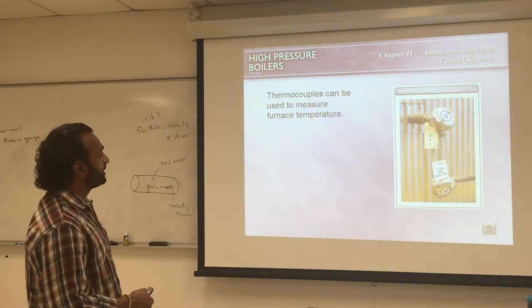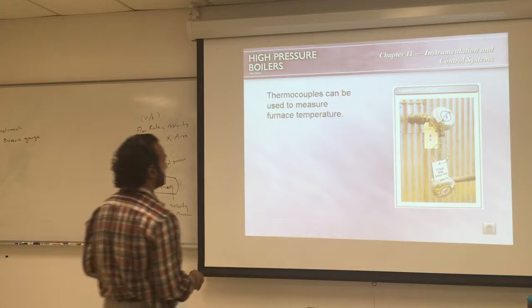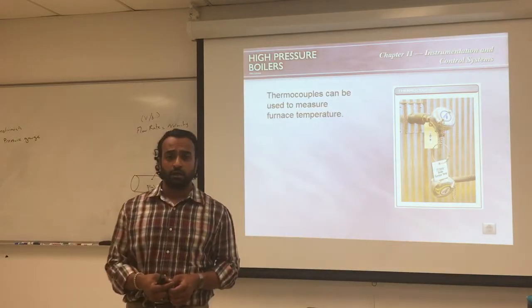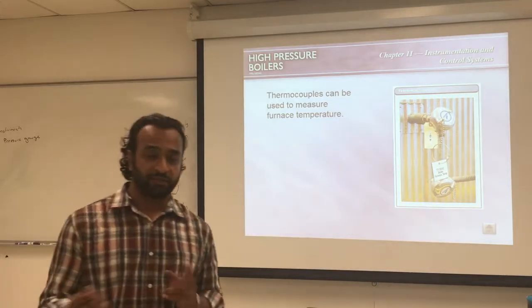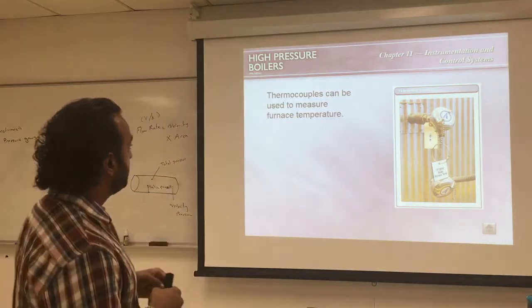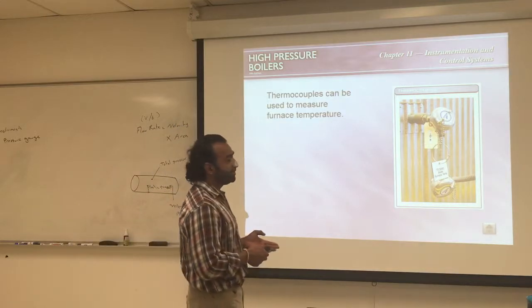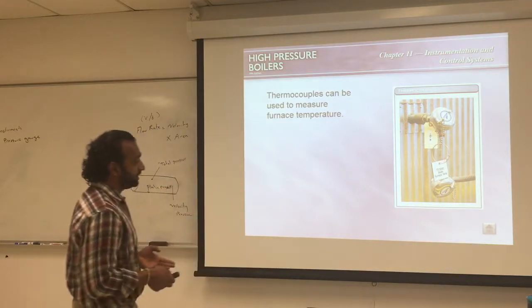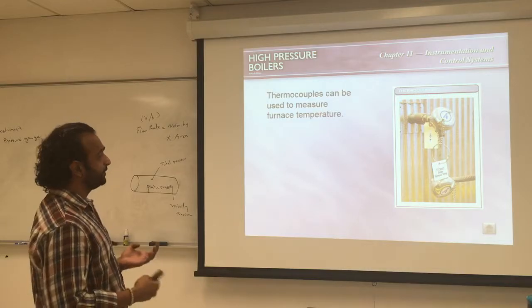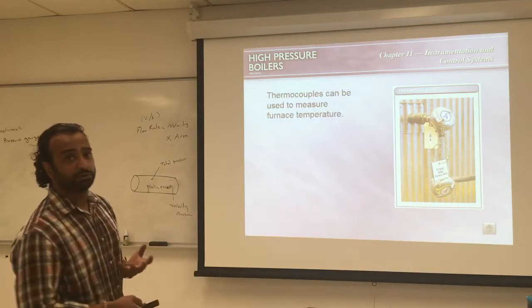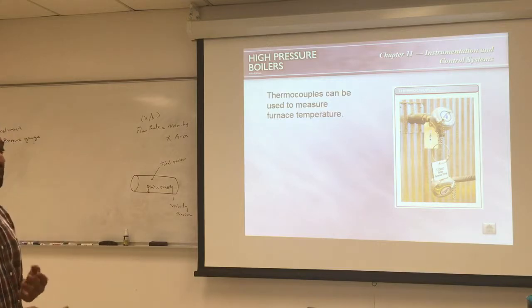Thermocouples, we mentioned thermocouples, is two dissimilar wires, different material wires, put together, and they produce voltage when they are exposed to heat. So they are very precise, they're very well calibrated, and they also can measure temperature over a high range of temperature, and their sensitivity does change from one type to another.